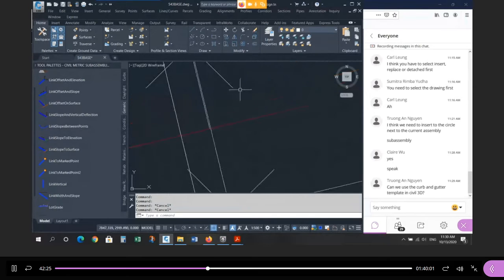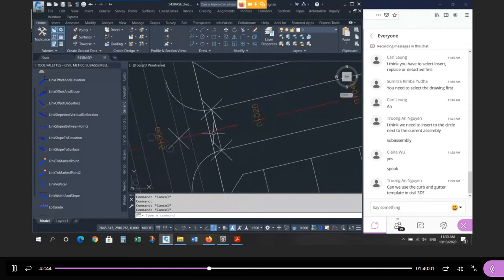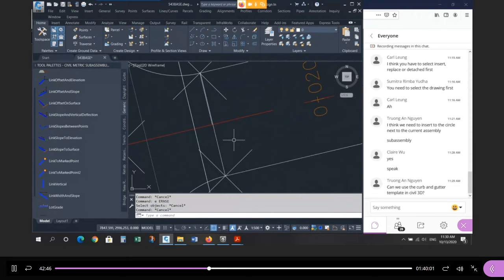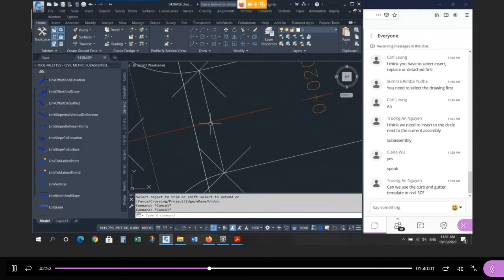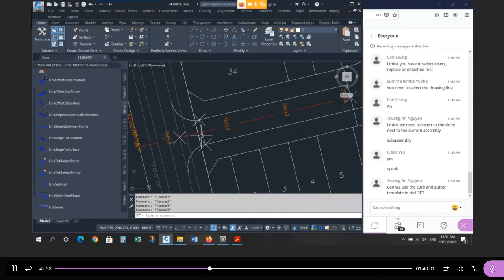Again, in my case, the one furthest away is this one. If you look at positive chainage, it's the right side of the road. It depends on your geometry. It might be the right, it might be the left. The general statement is whichever point is furthest away from the intersection into the site. My position is the same as yours, just the elbow is up way. It's not related to the subdivision, it's just related to the intersection. Yes, the one furthest away from the intersection is the low point. You ignore the other one. Okay.